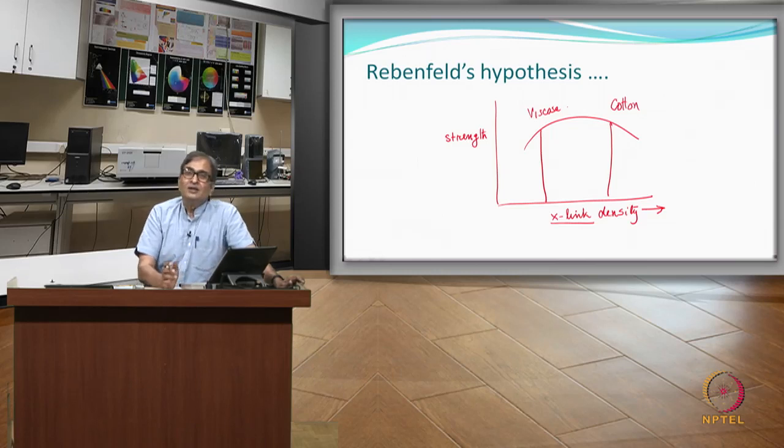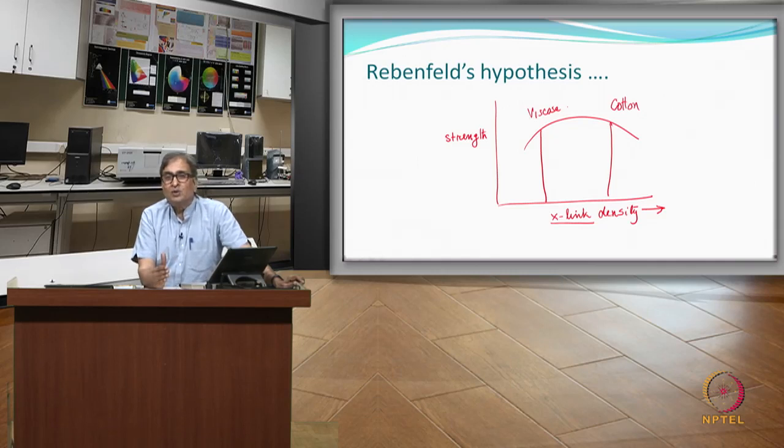Why? Because if we consider intermolecular crystallites which are there, which also resist any movement, are like crosslinks, those are very high in cotton. You remember, more than 2/3 of cotton is crystalline versus 35 to 40% crystallinity in viscose, depending upon what you do to it. It's a man-made or manufactured fiber, so you can manipulate the microstructure. So, what happens if this is true?